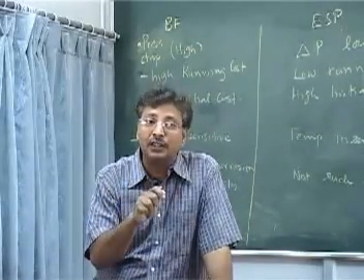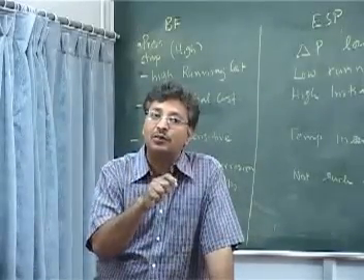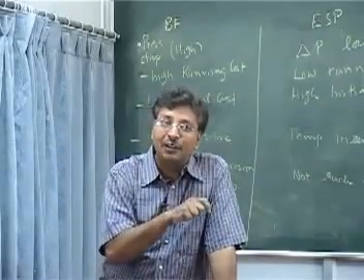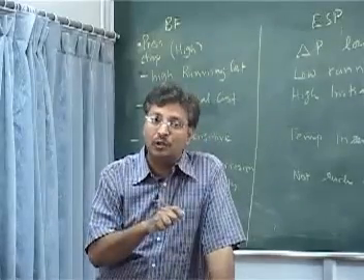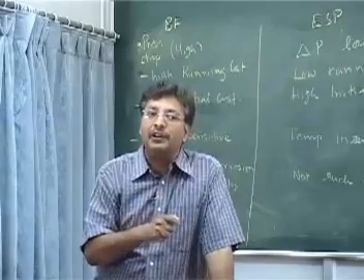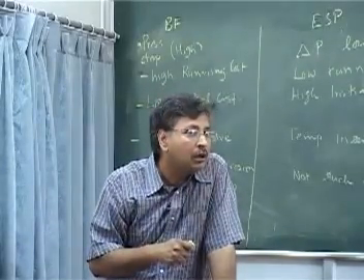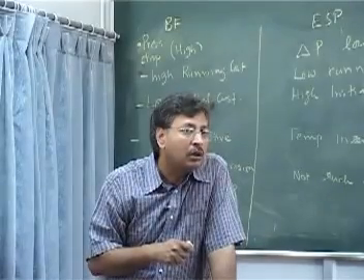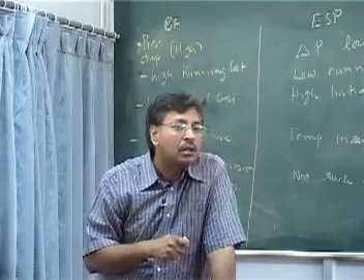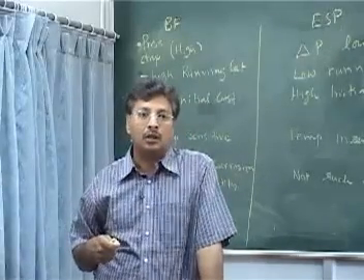The gases may contain water, but it is in the vapor form, and the SO2 will not be in the form of sulfuric acid, it will be in the form of SO2. And for SO2 to convert into H2SO4 is very difficult. What about water depositing on the metallic plates, where corrosion may occur? For corrosion we need just oxygen and water.